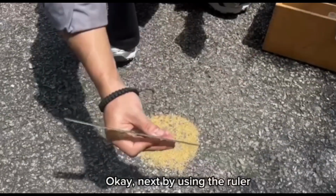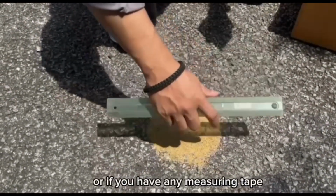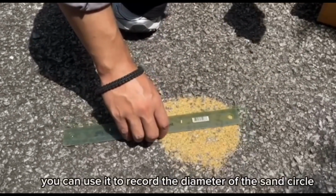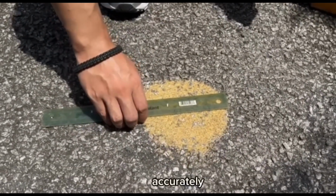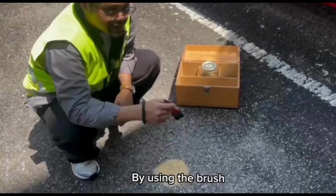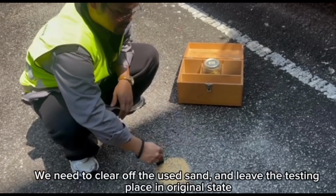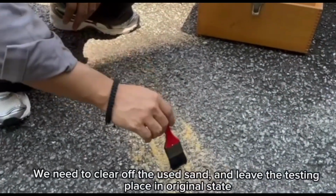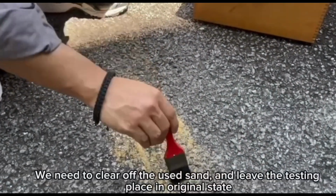Okay, next, by using the ruler, or if you have any measuring tape, you can use it to record the diameter of the sand circle accurately. By using the brush, we need to clear off the used sand and leave the testing place in the original state.